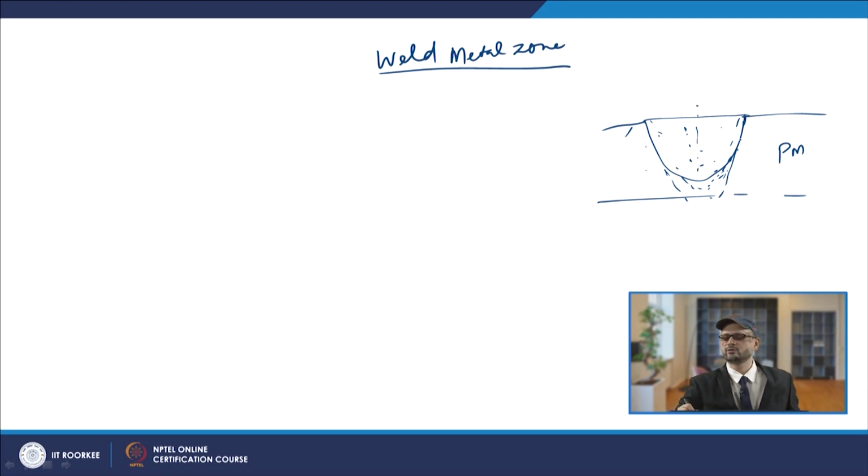So, this way, and we have already understood that you have all these partially unmelted grains which are there. They will work as the source of nucleation in such cases, and from them nucleation will start, and then it will grow further towards the inner side of the weld metal pool. This mechanism is also known as the epitaxial mode, or epitaxial solidification, or epitaxial type of growth.